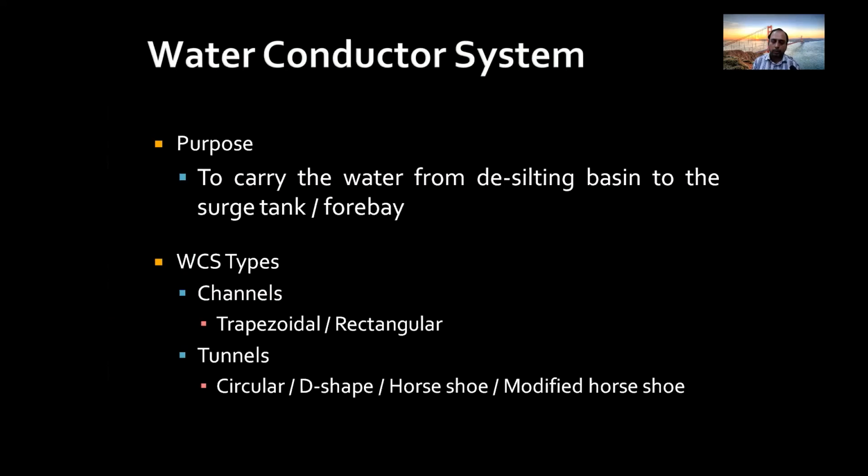You can also have trapezoidal. Trapezoidal are preferred for large channels. For small channels, you can also go for rectangular. And tunnels can be circular, D-shape, horseshoe, modified horseshoe, or so on. It can be square also for very small tunnels.